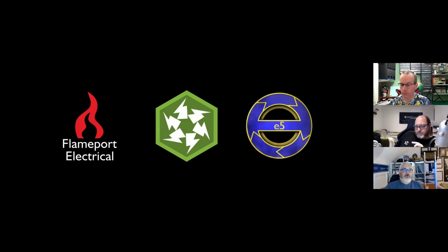Now, why just fault? Because it's fairly evident, if you looked at the picture last week, the diverted neutral current issue, it's not fault, it's normal. Diverted neutral current is large levels of excessive neutral current appearing on earth systems, which can cause temperature rise. That's in BS 7430. So I'm reading that.